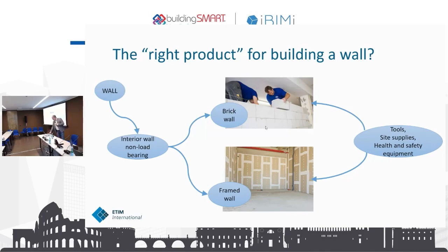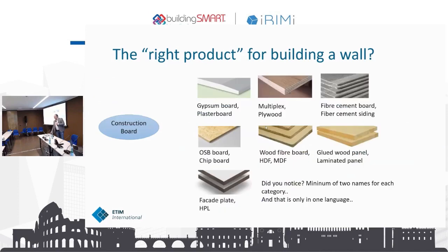So you end up with a lot of requirements for products. And then if you say, okay, we'll go for a framing, do you use steel framing or wood framing? You could also have a choice for construction board. You could use plain gypsum, but you could also use waterproof gypsum board, or maybe fireproof fiber cement board. Every product choice has consequences for the results. And if you specify results, also the requirements for the products change. And you need to find the right product, right?